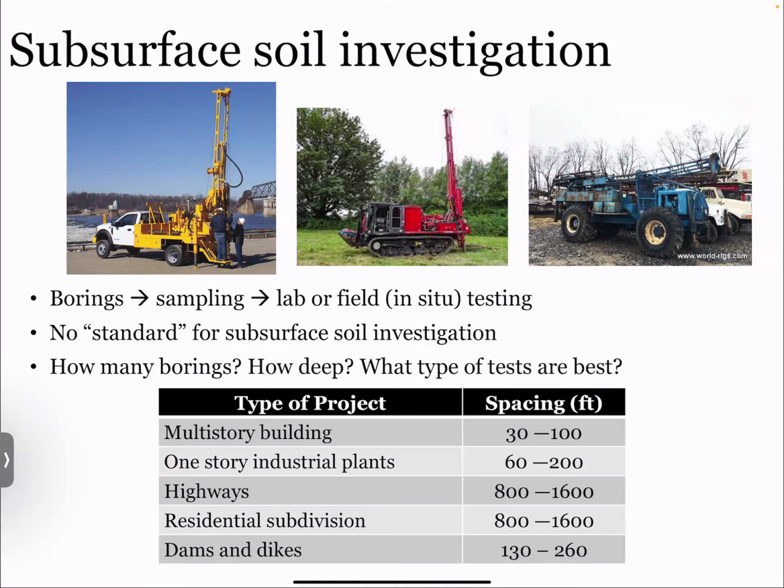But just to put into perspective for cost, to mobilize one of these trucks out here with a drill crew and to drill like a, I don't know, a day's worth of 60-foot borings, like 60 feet in depth, so not even that much, that mobilization usually is around $10,000. So like that times whatever, months of testing, it can get really expensive really quickly. So obviously you don't want to go out and bore every 10 feet, even though that would be nice, because then you would get a lot of information about your site.